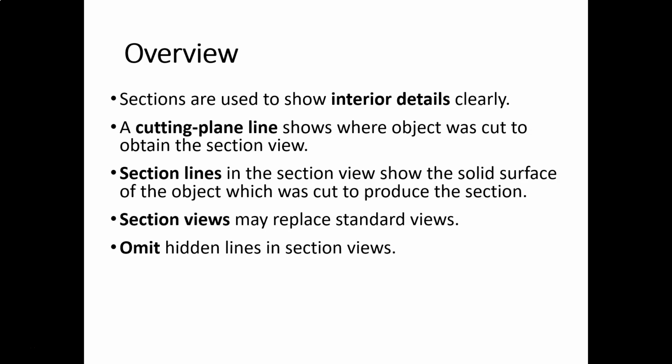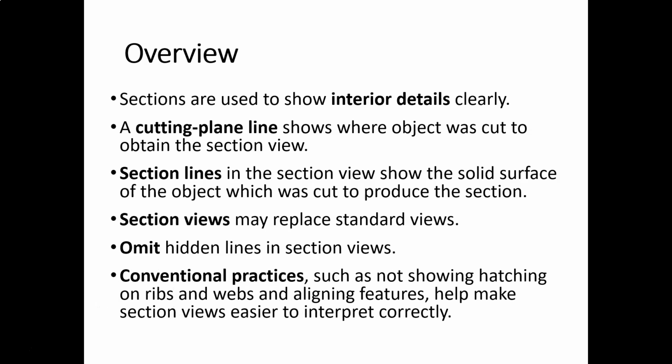Now, let me be very clear. When we talk about omitting hidden lines in the section view, we're talking only about the view that is the section view. Not the other views, not the views that have the cutting plane line, only the section view.